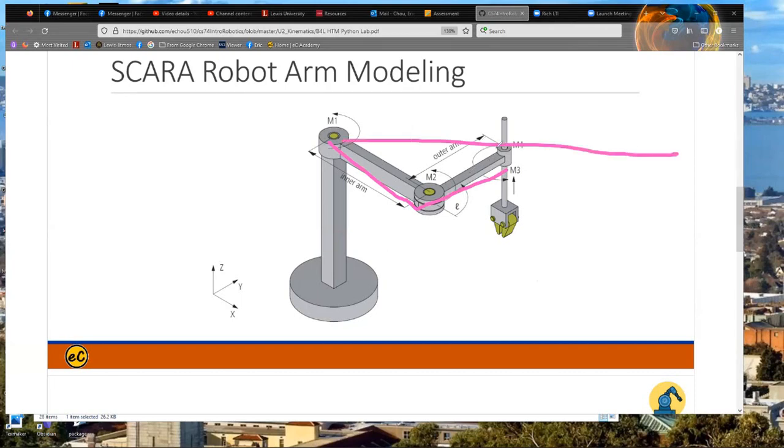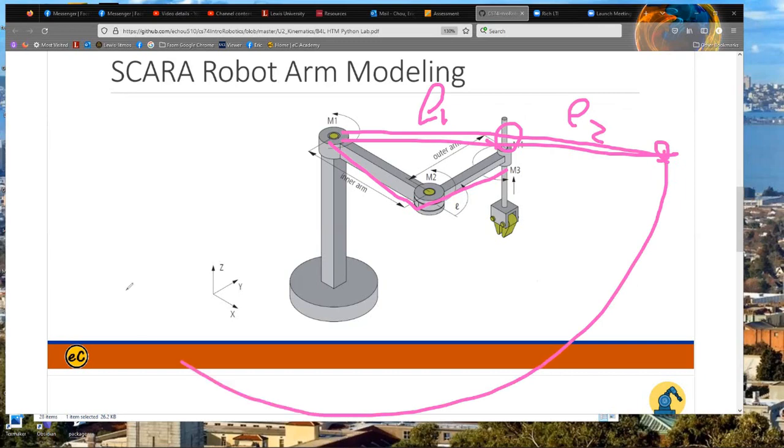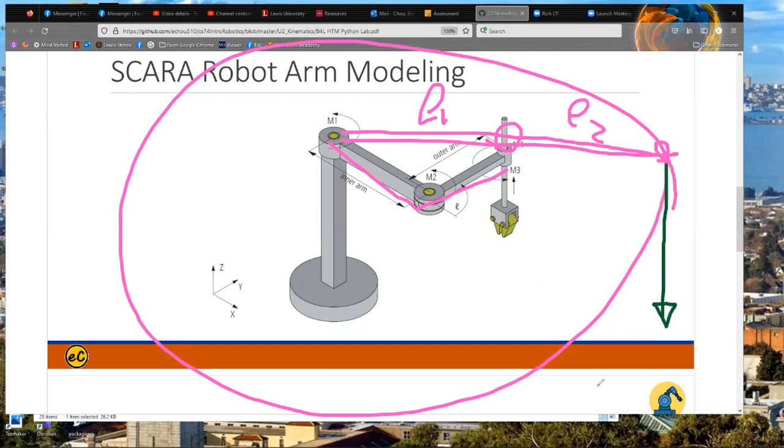If we use the baseball bat configuration, making it the longest one, L1 plus L2, then it will make a circle here, on the same plane, and then you will be able to go down. If the lengths here and here are 1, 1, 1, I say you just need to set the links to be 1, 1, 1, meaning 1 meter each. Just pick it as simple as possible. And for the initial condition, this one also extends for 1.